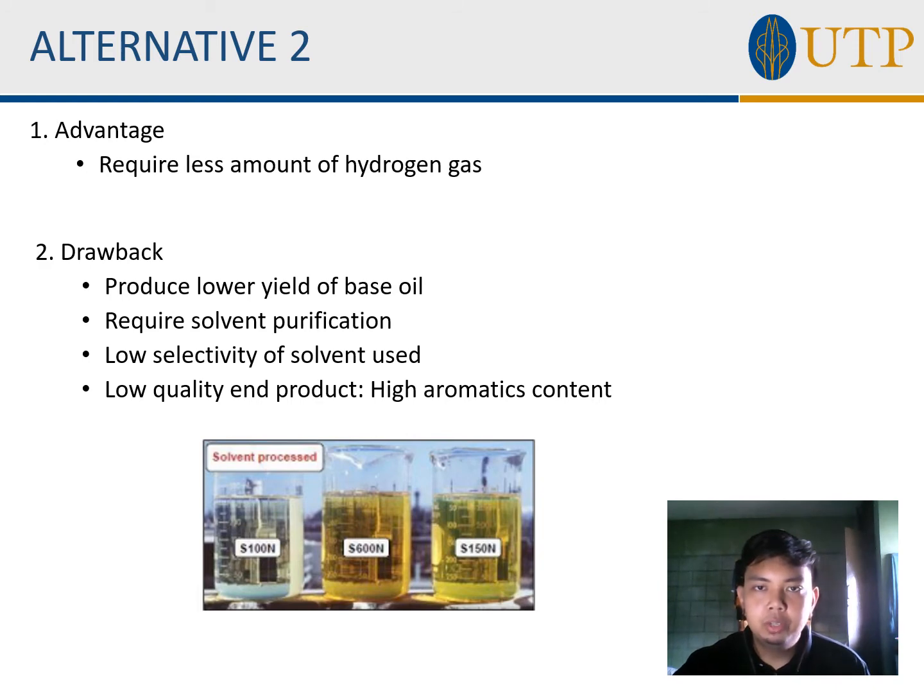For alternative 2, it only has one advantage, where it requires less amount of hydrogen gas because this alternative is an integration of solvent extraction, solvent dewaxing and hydrofinishing. Hence, it only uses hydrogen at the hydrofinishing part.